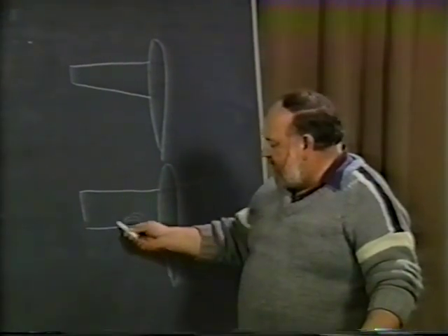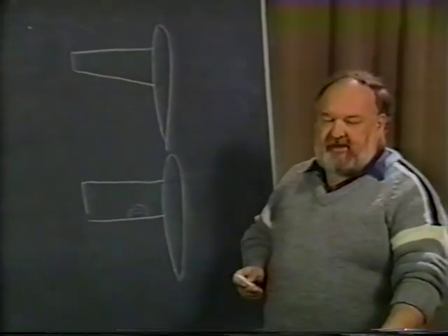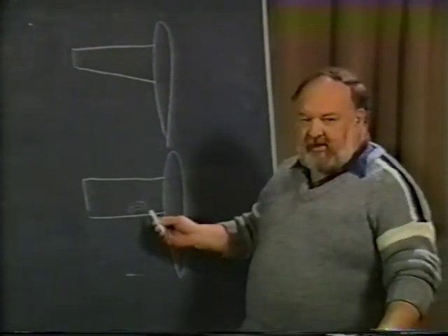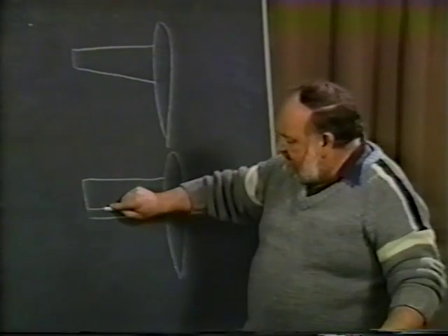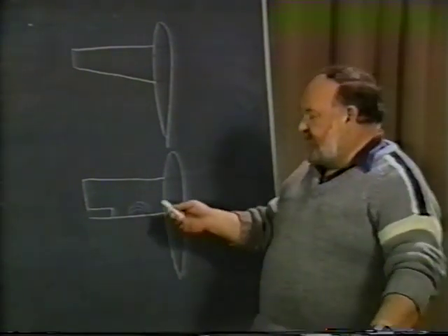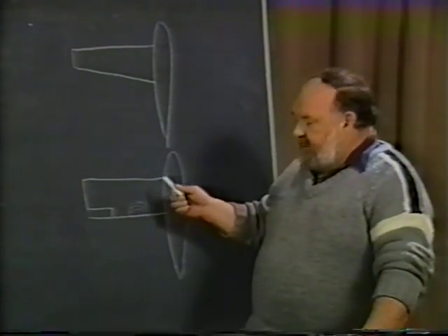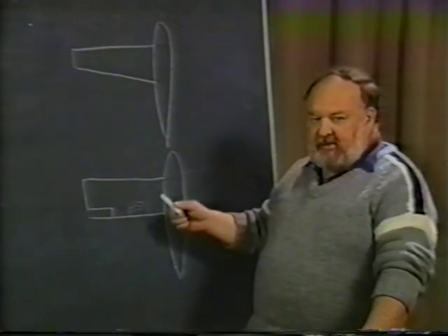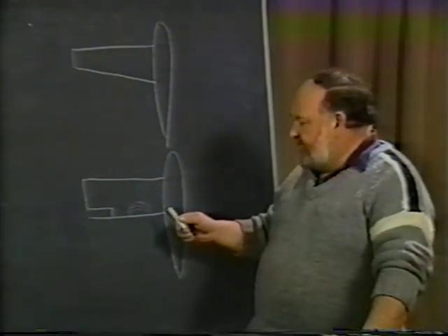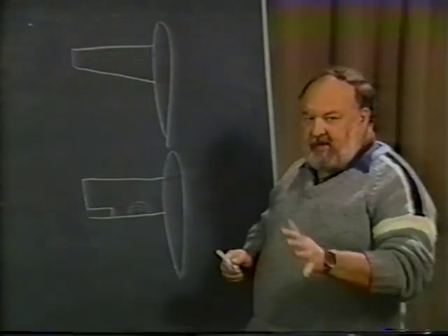If we could let the stall begin here, in this portion of the wing, not necessarily right up against the fuselage, but inboard fairly close, definitely away from where the ailerons are. The factor that comes out of that is this: if we are approaching stall and the airplane gets near its point of maximum lift and the stall begins here, the airplane will not tend to drop one wing or the other.